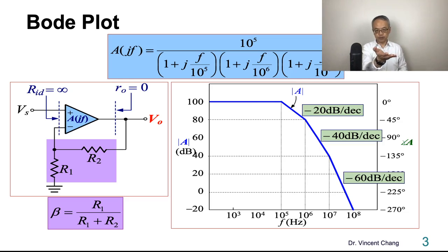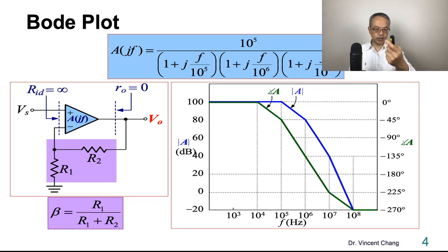Here's the magnitude response. What about the phase response? So here's the phase response. 4 segments: 45, 90, 90, and 45. And the rest, negative 20, 270 degrees.